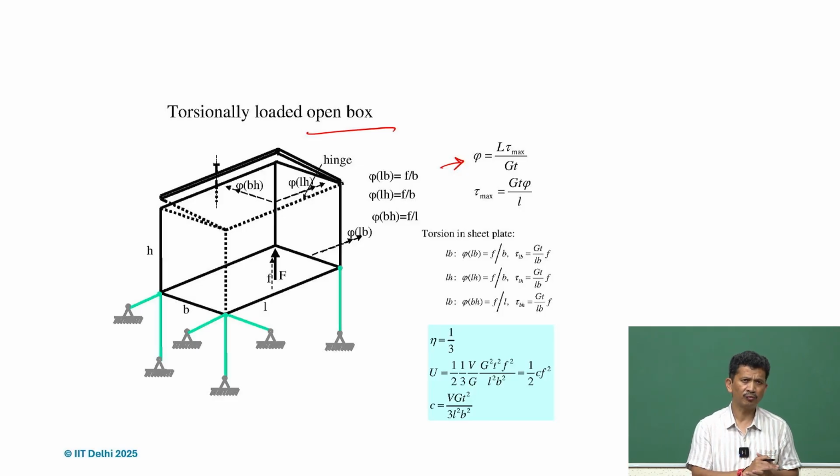At the same time, we can also look at the design, and since it's a parallelogram structure, what we also realize is that parallelogram structures are not exactly constrained. There is always one diagonal along which it can move, and therefore the moment one load is acting at the end, we realize that it's not stiff.